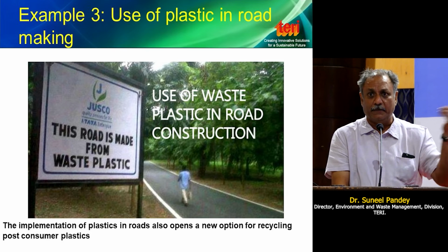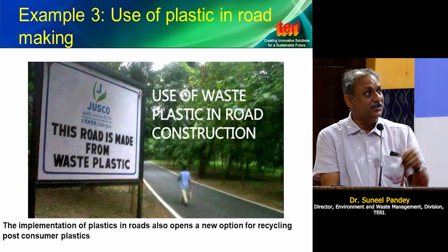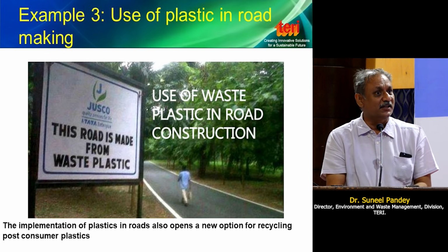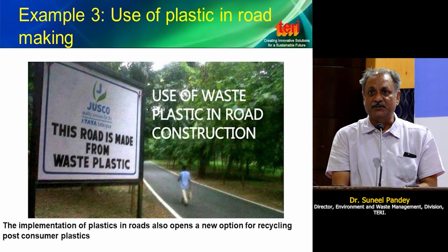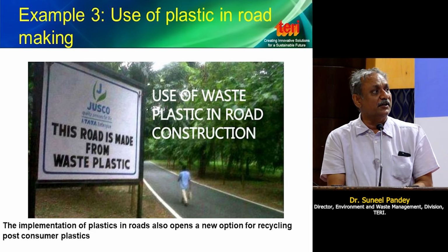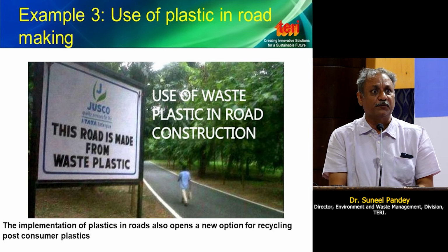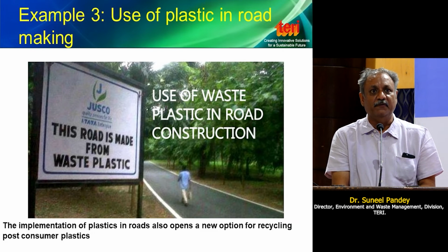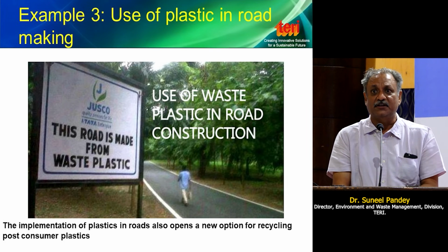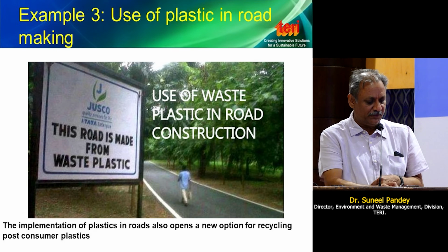Plastic waste, here also in Trichy, in Tamil Nadu, it's happening at a large scale. Plastics which cannot be recycled, the dirty plastics, we say difficult to recycle, and single-use plastic as per government definition, can be shredded, mixed with bitumen, and used in road construction. Experience has shown that roads constructed with bitumen mixed with plastic waste last much longer. This road in Jamshedpur was a test road, which when we went 3 years back to the city, they showed us. They had constructed it around 5 years back, and this road was still serving them well.